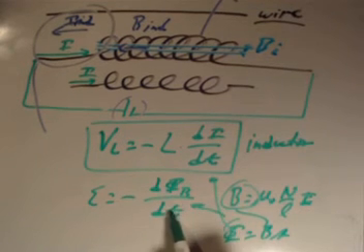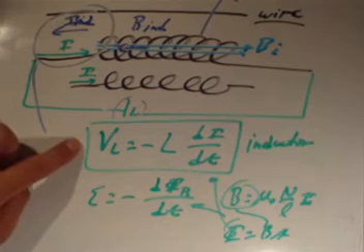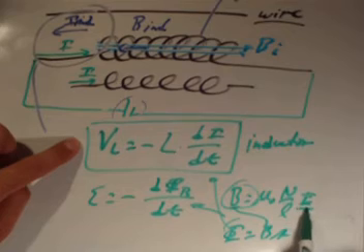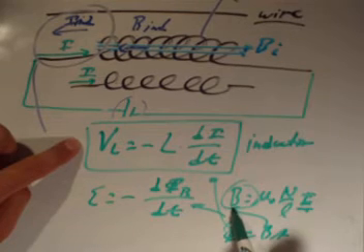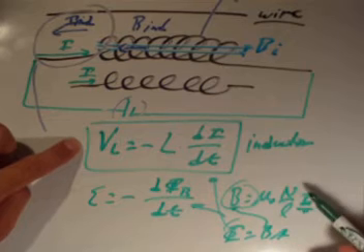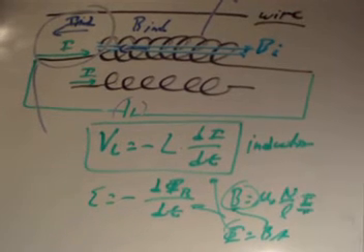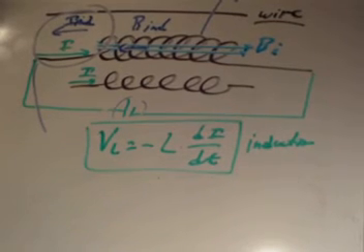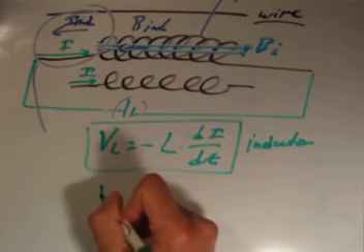You put it into Faraday's law and take that time derivative, and you'll eventually see that everything boils down to the change in current, because even in the equation for the solenoid, the current is the key driving term, so a dB dt is going to have a di dt if it's going to be non-zero. We don't expect a time rate of change of the number of turns or the length, unless you're doing some sort of bizarre problem. So you do have a key inductor equation like this.